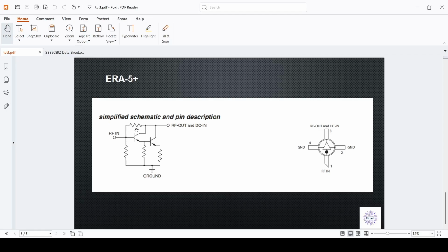But you can also use the same bias feedback resistor to create that 50 ohm matching, because now Miller effect comes into the picture. If you want to see this resistor's effect when you look at the base, its effect is divided by the gain of the circuit. So essentially, you will see this RF divided by your gain.